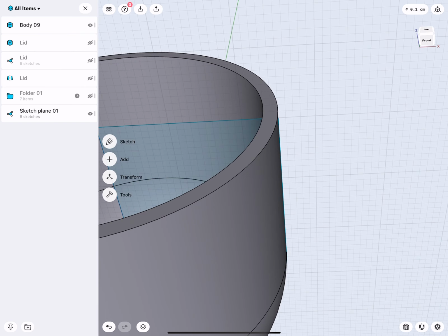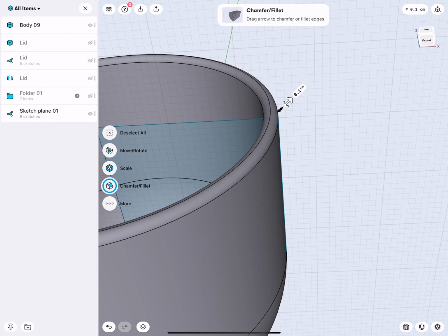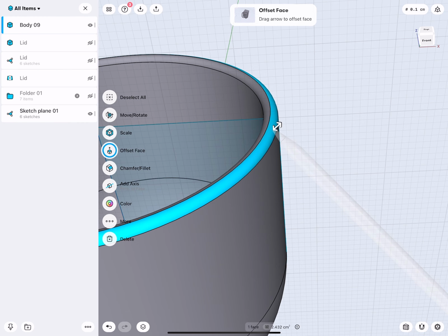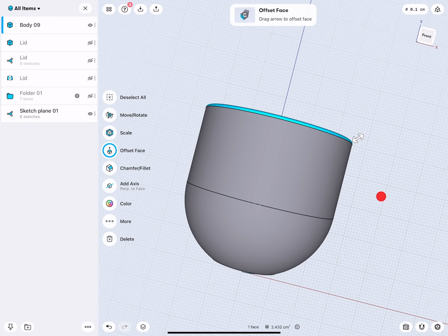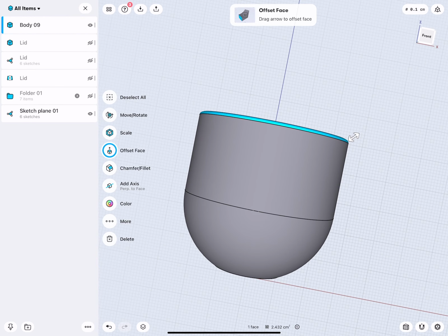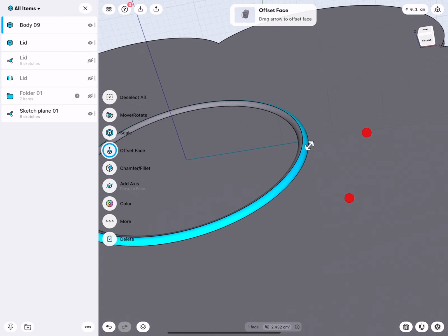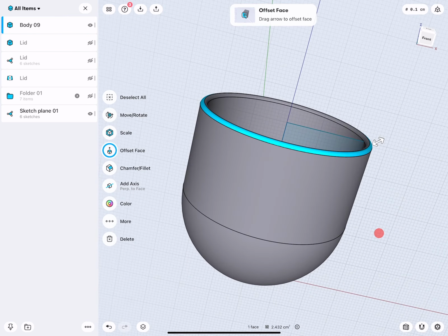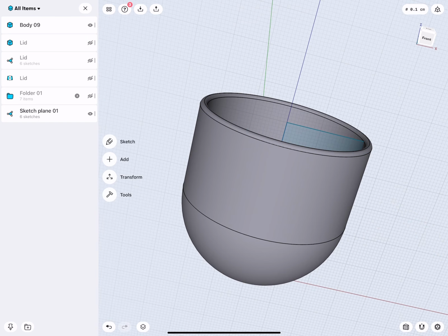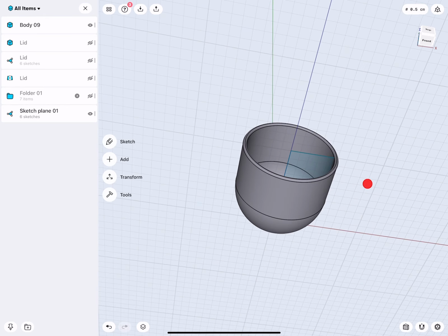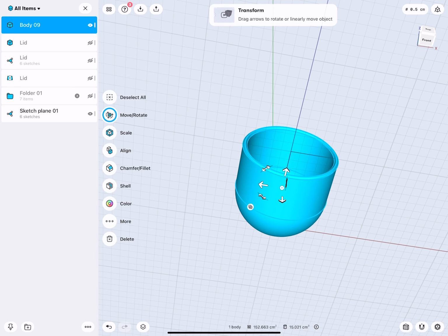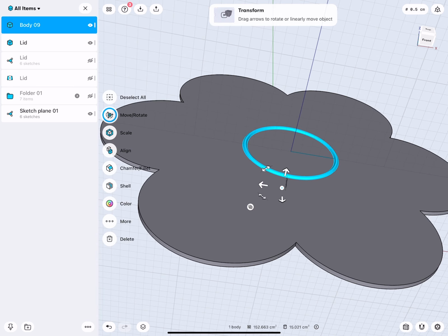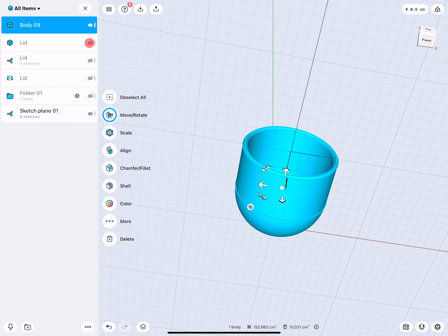And these 2 edges will be rounded. Because this is a 2 millimeter material thickness, each fillet radius can only be 1 millimeter, so I moved it up by 1. Because a circle with a diameter of 2 millimeters has a radius of 1 millimeter. You see, just the rings stick out. Okay, very nice. So this is good so far, but how do we solve the problem that when we multiply this cup by 2 and join it to the lid, how do we get the center part open? Let me show you how we solve that problem.